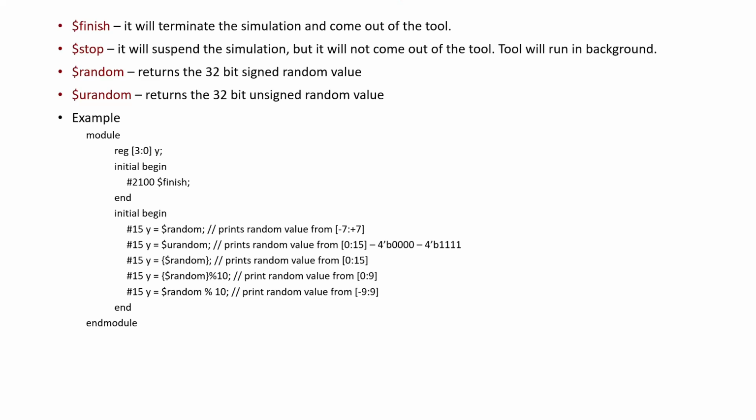So $finish, I told you, if you want to terminate your simulation, then you can go for $finish. And $stop will not terminate the simulation; it will just suspend the simulation, like pausing a video. If you are playing a video, you want to pause that video and then again listen to that video from wherever you paused. At that time, you can use $stop. It will not terminate your simulation; it will suspend your simulation. If you again want to run the same code, you can resume that code and then it will be executed.